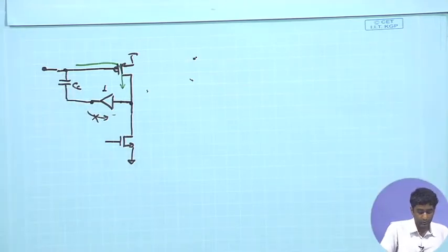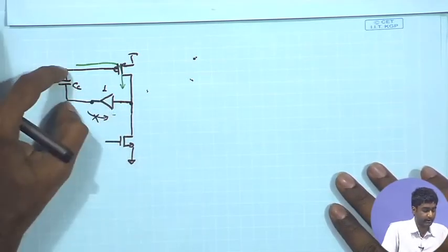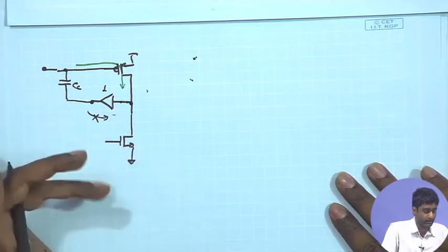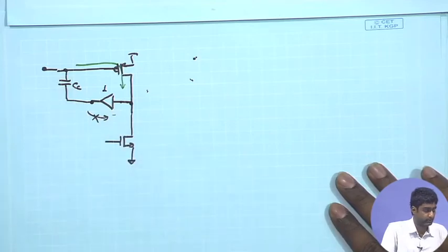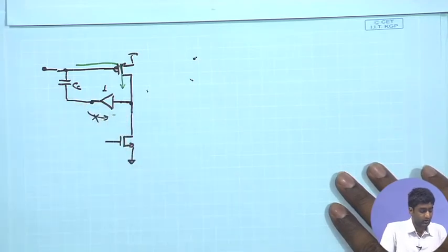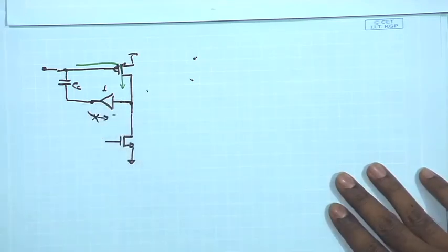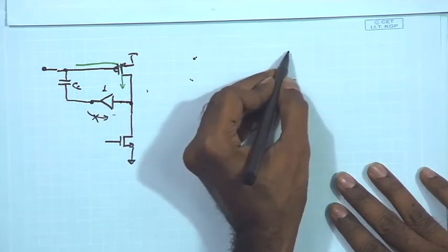Therefore, this is able to compensate the overall two stage response by still exploiting the Miller effect and getting the CC multiplied by a large number. At the same time, it is also blocking the second path and hence helping us in achieving the overall cancellation of the zero. Now, in order to implement this particular amplifier, as I said, the simplest strategy involved is to use a common drain amplifier. So, we can think of inserting a common drain amplifier.